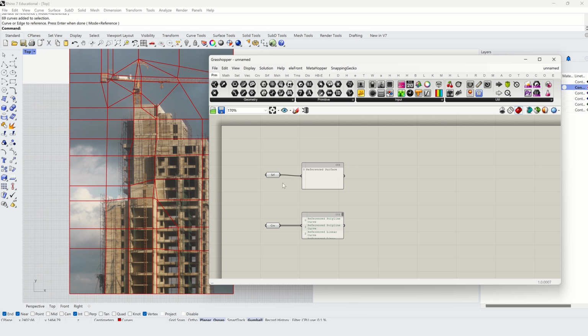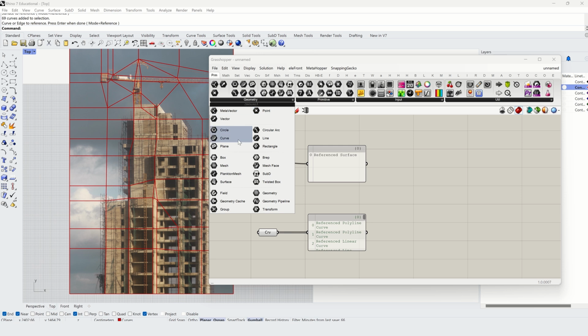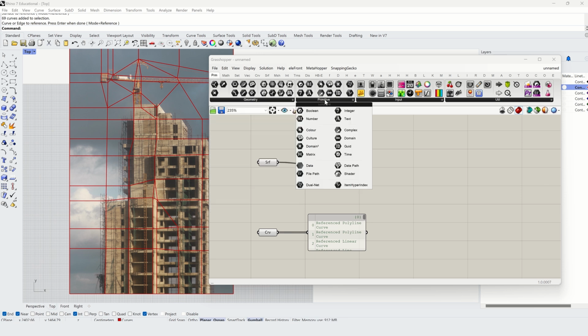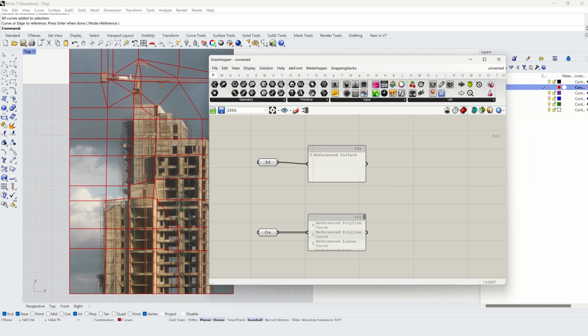In Grasshopper, inputs always enter on the left, outputs are always on the right. Every component either holds data, outputting the same information, or it operates on the input, outputting new information. Params are components that normally only hold data, so it is natural to have them at the beginning of an operation to hold the initial conditions, whether geometry, numeric parameters, or something else. Hide the Rhino layers now.